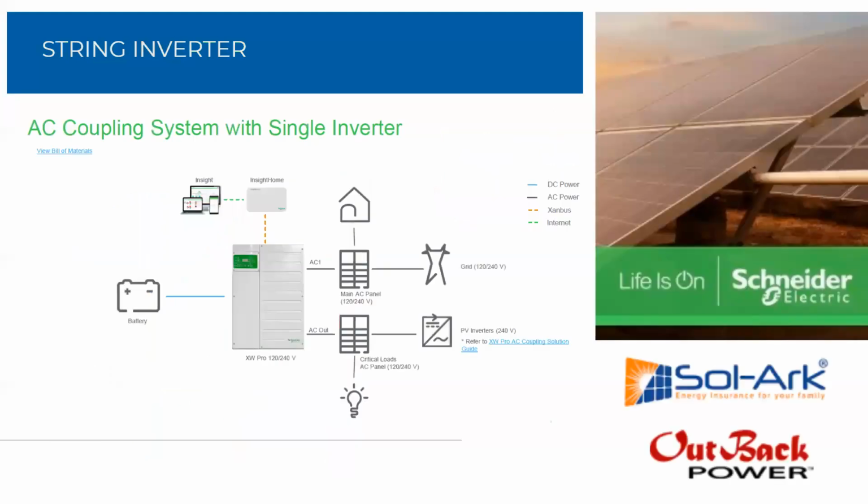String inverters. Okay. AC coupling with string inverters has also been going on for a very long time, even longer than we've seen the StoreEdge with LG Chem. So let's review. Very similar to what we looked at before. We have our panels. We don't actually have our panels displayed here, but our panels are feeding our PV inverter. This is our PV inverter icon. And that is feeding, again, our critical load sub panel.